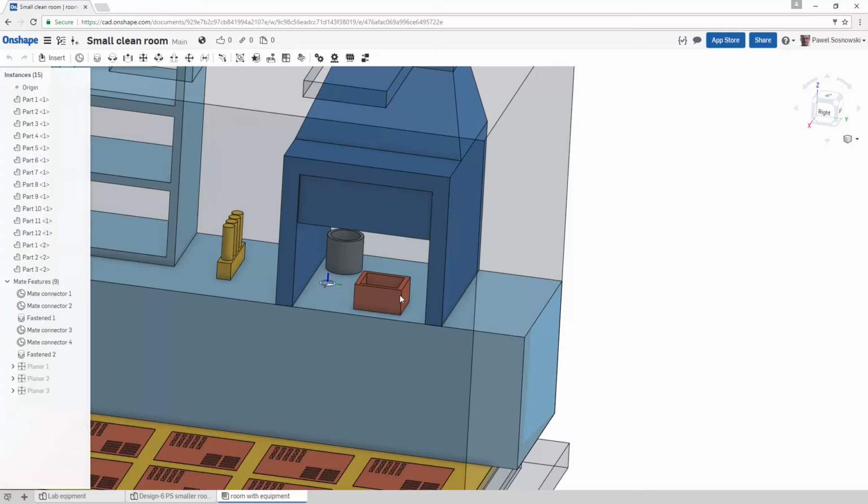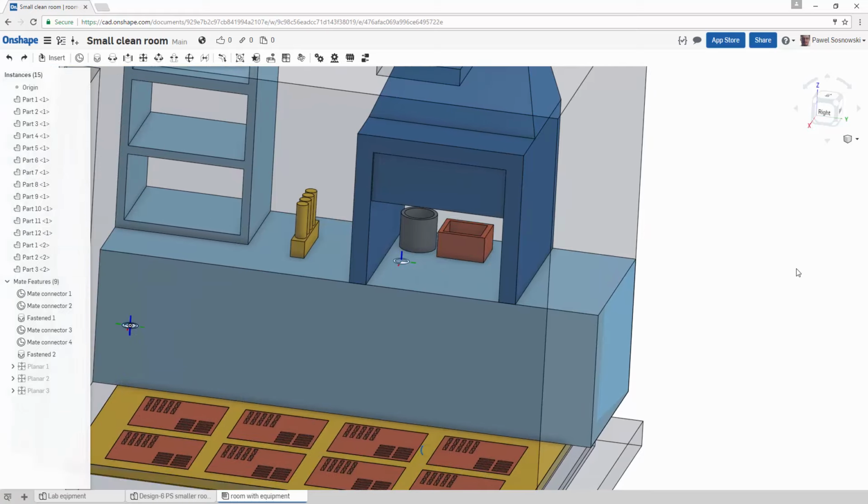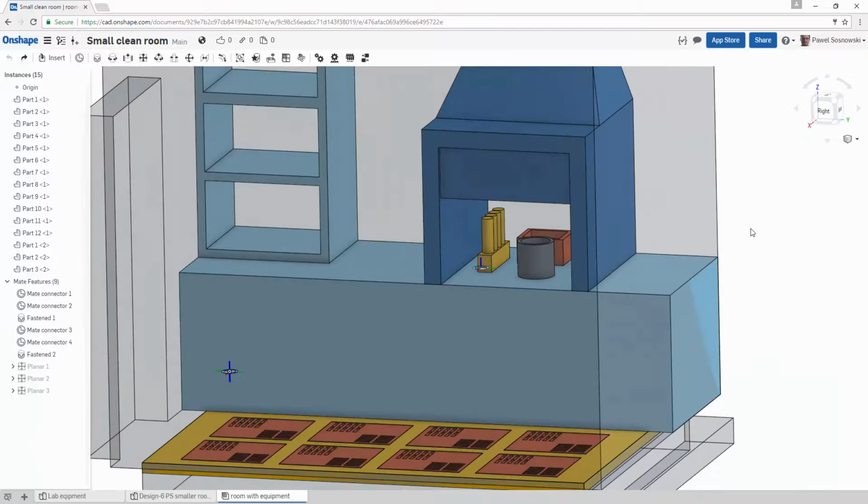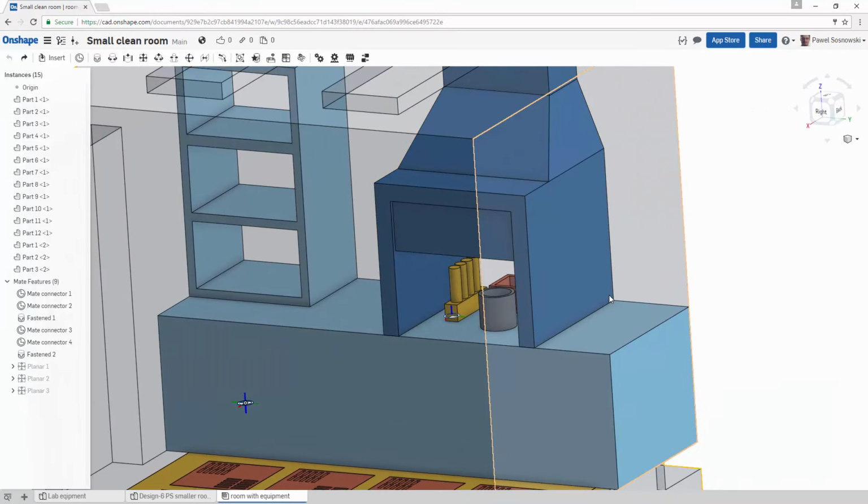The downside of this approach is that whenever we make modifications to the geometry itself, we will have to remesh the geometry. Whenever we move something, we need to remesh it and rerun the whole simulation. But with the general setup that we've done before, we can do that with relative ease and pretty fast.